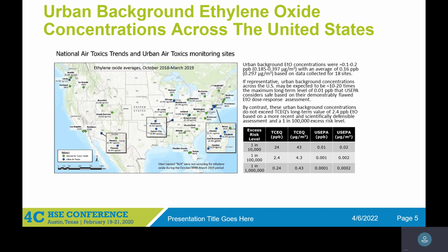While the TCEQ recommendation for 1,3-butadiene is now 10 times more than background, so it's logical. There is instrumentation that can measure it. So it's really problematic, like my previous talk said. How can you give a threshold that no one can measure? And if no one can measure it, how can you control it? If I was the one making the decision, I would go with TCEQ, with something you can measure, something 10 times the threshold, and not go to a number that no one can measure and follow.